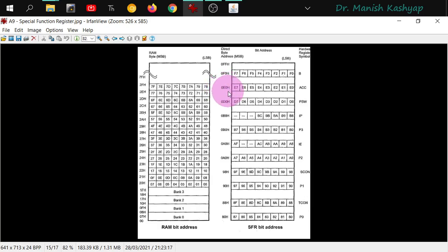We will see that it is necessary because in 8051 we will also study pointers, right? So you can either refer to the accumulator by its name A, or you can just keep its address in some other register, and those other registers are only R0 and R1, and you can manipulate the data which is kept in the accumulator register, right?